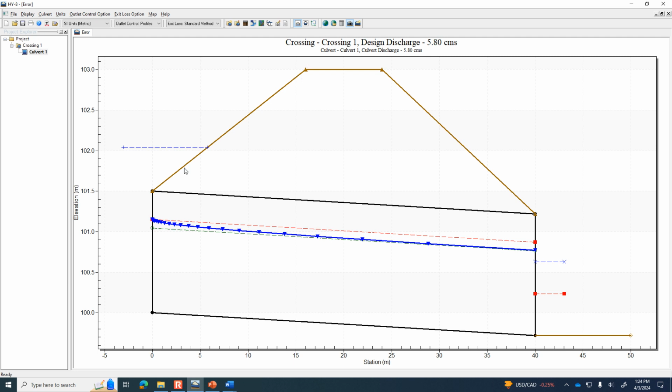And this is a pretty typical thing, that if you do have a culvert, you may have soil beneath the road, and so you can't have soil with a vertical slope. You'd maybe have to have a tapered slope leading up to that. So typically culverts will be longer than the width of the roadway. That's why the example that we were working through on Monday was just a vertical face, but here the roadway width is quite a bit less than the culvert length. So that's why we've got that trapezoidal shape on top.